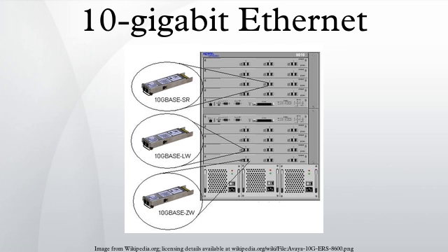The 10GBASE-LR transmitter is implemented with a DFB, or distributed feedback laser. DFB lasers are more expensive than VCSELs but their high power and longer wavelength allow efficient coupling into the small core of single-mode fiber over greater distances.